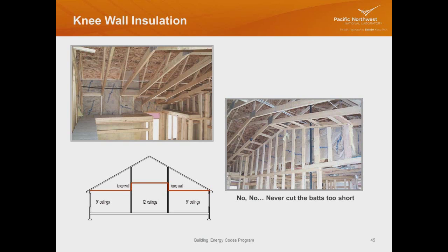So with the insulation, if it's all one application, if I'm blowing in R38, I show that all as cavity insulation. I don't break out my insulation and show this much R value above the trusses and this is R value that's in between the framing members. REScheck already makes assumptions for the ceiling based upon the R value entered. If I enter R38, R49, it's running a series of calculations in the back end.